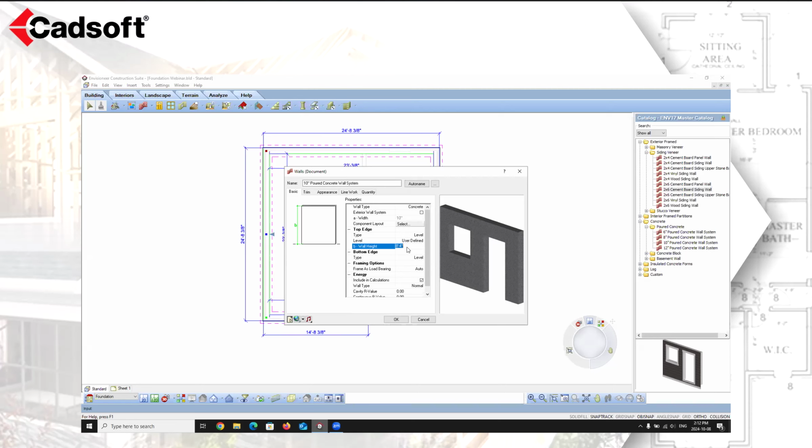So if I drop this wall height to be 8 foot 4 inches, and I got rid of the 4 inches, I would need to elevate the wall up 4 inches because it's measured from bottom of wall to top of wall. If I take away 4 inches, I'm essentially just taking it away from the top. So I need to elevate it up to bring that 4 inches back into play so that the floor structure sits on top of the foundation wall itself.